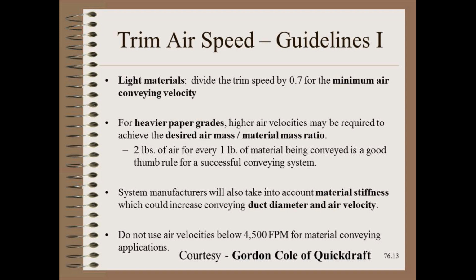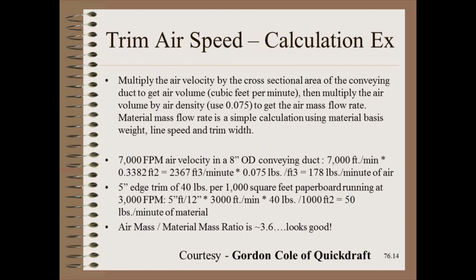To this, we have many other quite important details that affect design, including material stiffness. However, the most important other detail is for a minimum airspeed of 4,500 feet per minute or 1,500 meters per minute, no matter what. This slide shows the example calculations typical of a high-speed paper winder.